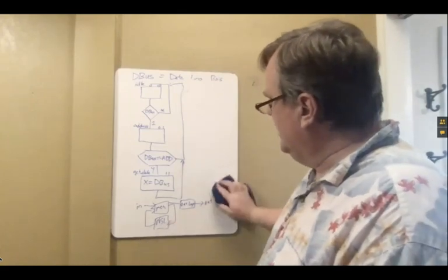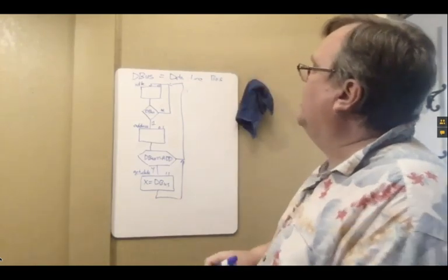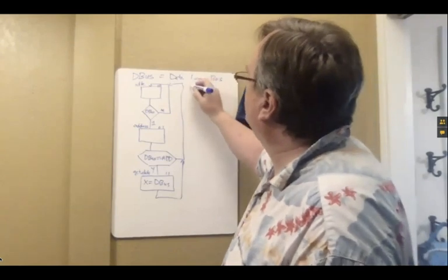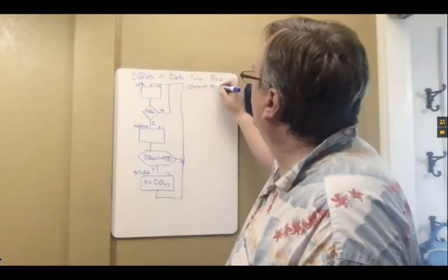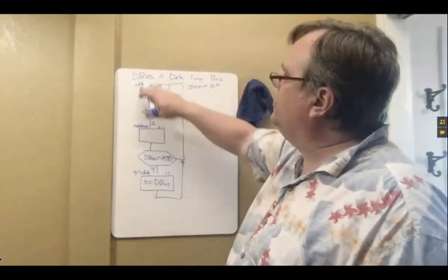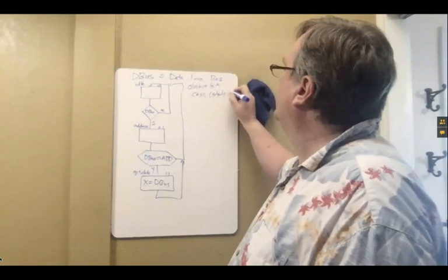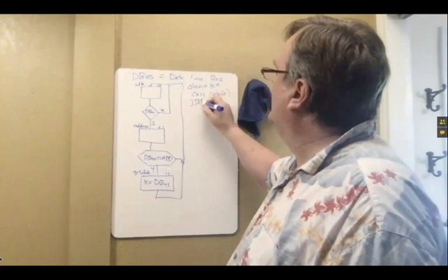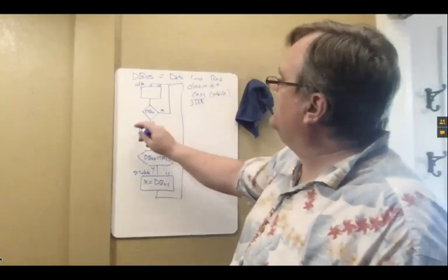Now we're going to do the last one, the next state logic. I don't need that picture down there either. All right. So this one is going to be my next state logic. It is combinational. So always add star. Now in this case, it's going to be very simple. I'm going to use a case statement. Case my state, and then I can say for idle. And what do I want to do inside idle? Now I can just look at idle.